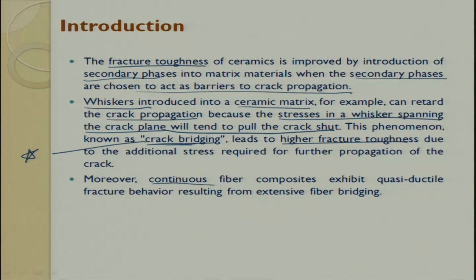When we are using a continuous fiber composite, it exhibits quasi-ductile fracture behavior resulting in extensive fiber bridging. But please understand, reinforcing a ceramic fiber into the matrix is really a challenge while manufacturing. It is very easy to manufacture particulate type or whisker type ceramic matrix composite.